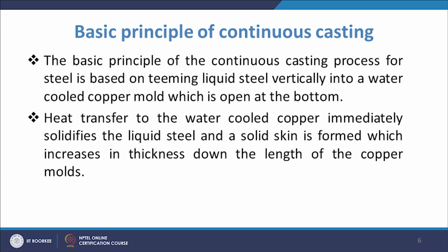The mold is made of copper. Heat transfer to the water cooled copper mold immediately solidifies the liquid steel, and a solid skin is formed, which increases in thickness down the length of the copper mold.